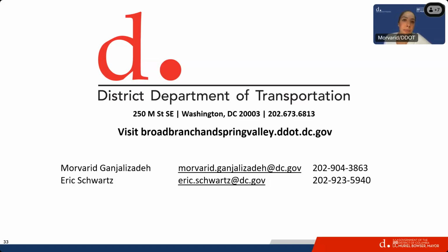About the slope, we can have the bioretention on the slope. We consider 8% longitudinal slope for bioretentions, and for the permeable pavement it is 5%. So if the slope of this street is up to 8%, we can propose a facility. If it's more than that, we remove it. I will come talk to Carol and George next week, if this question is from them. I got more comments and emails from 28th Street, so I can get back to you more when I talk to Washington Gas.